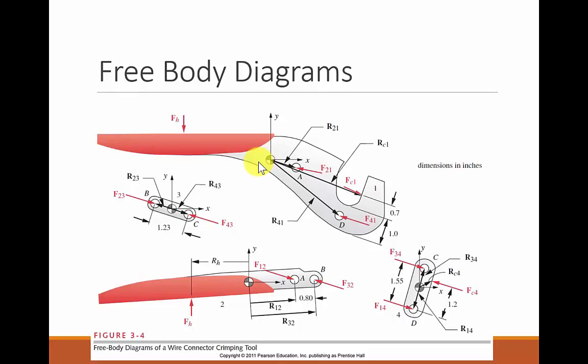And now, how many equations of motion do we have in this problem? So each body has 3 equations of motion. So F equals ma for each of the bodies. So that means there are a total of 12 equations that we have to govern. And this is again taking the understanding that we're in the plane. Okay, so we have movement. Each body can move in the x, it can move in the y, that's 2, and it can rotate about the z, that's our 3rd. So there's 3 equations of motion for each body, and there are 4 bodies, so there's a total of 12 equations of motion.